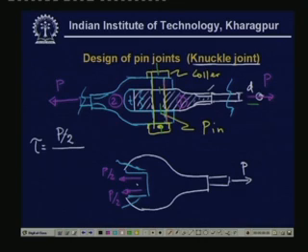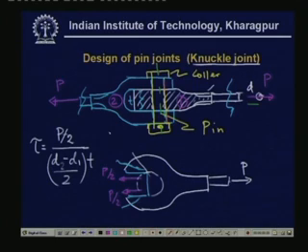divided by, this is the average shear stress, this is divided by this length, and this length, although it may look complicated, but making some approximations, this length could be taken as the same, that is this one can be taken to be the radial length, which is equal to D2 minus D1 by 2 and times T. So this is the shear stress.